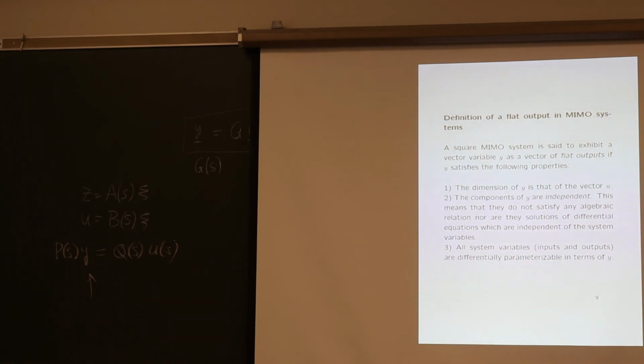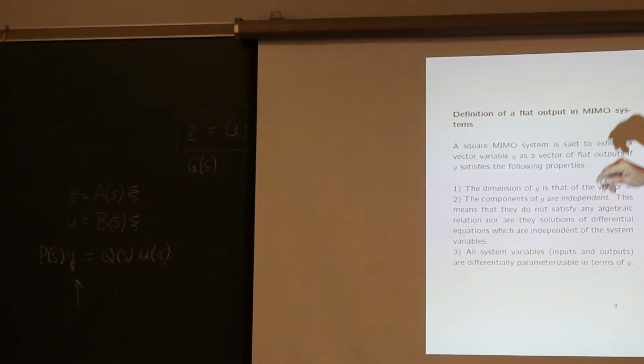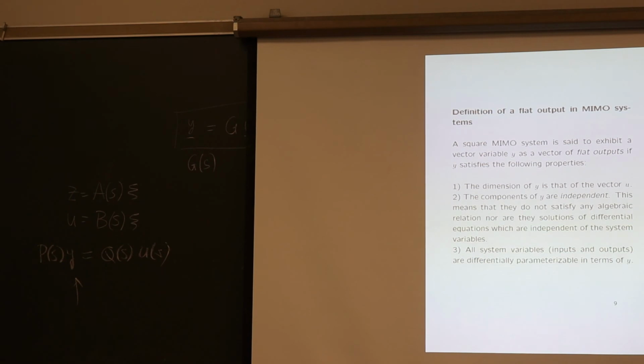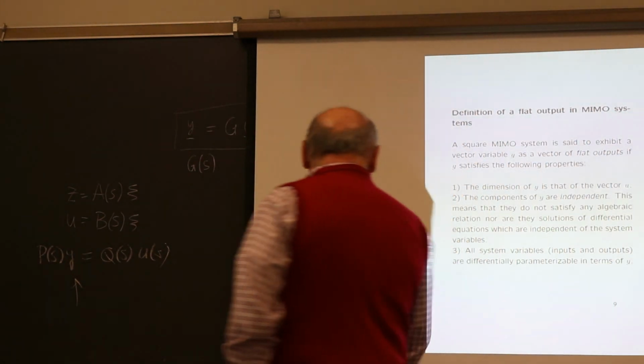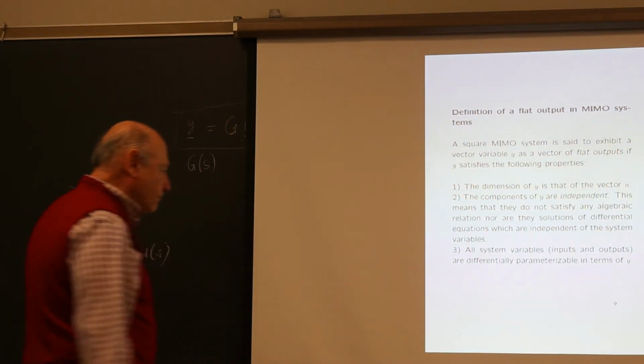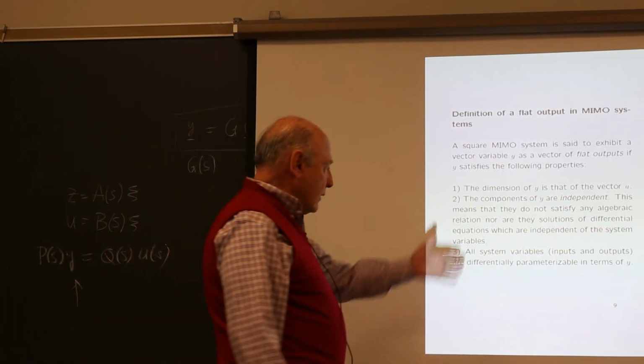So these two conditions are very important. The dimension of the output has to be the same as the dimension of the input. Second, the components of y cannot satisfy differential equations by themselves. And third, all system variables can be differentially parameterized in terms of y. So y is a flat output,